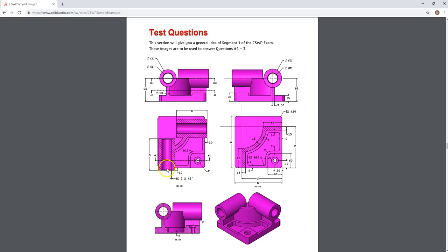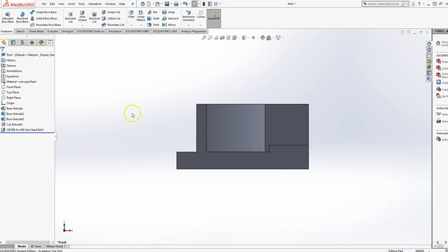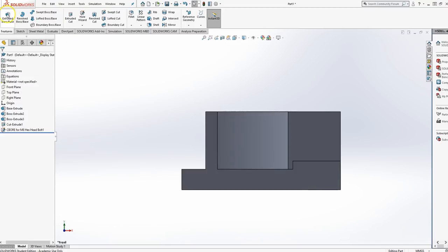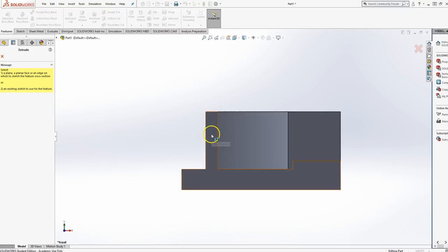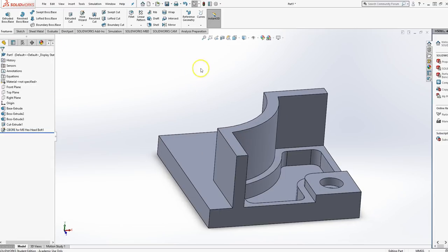That's 10 out, and then we're going to draw our circles on those planes. That way we just have to extrude one way, one dimension. Alright, so here we go. Let's get the front view here, and I'm going to do an extrusion. Oops, can't do an extrusion yet. Sorry, I have to put my reference geometry on first. So let's go ahead and do that.